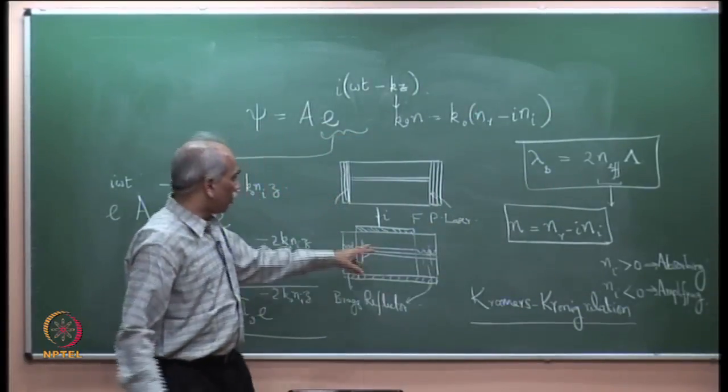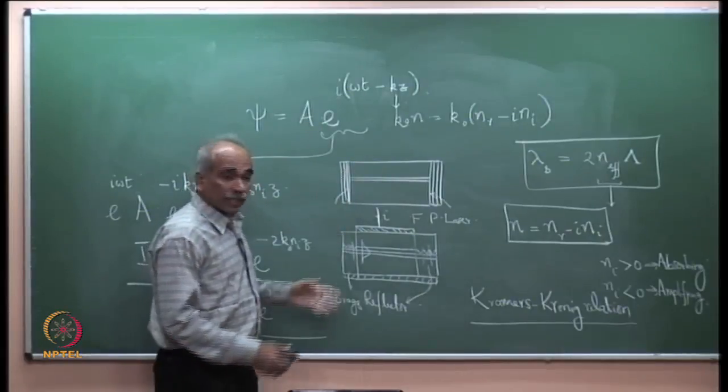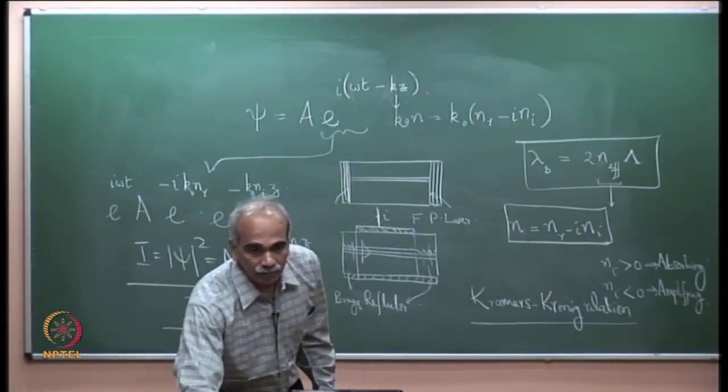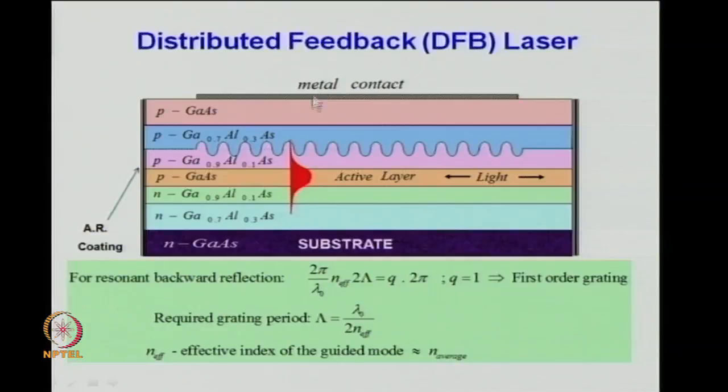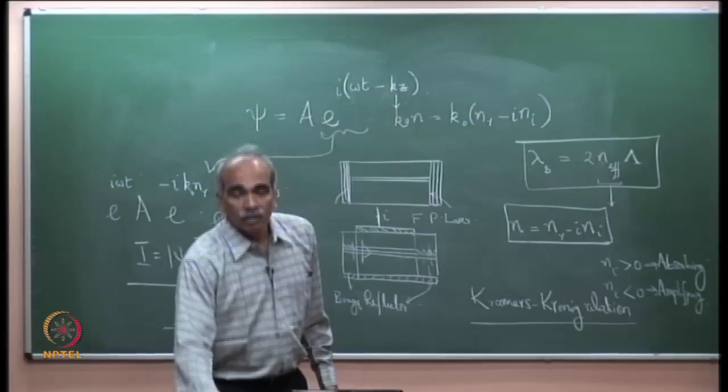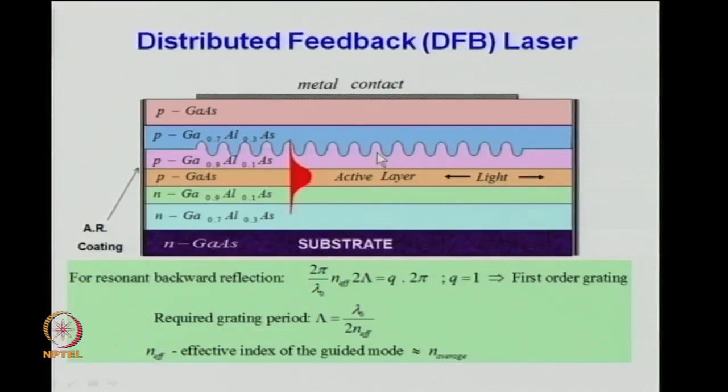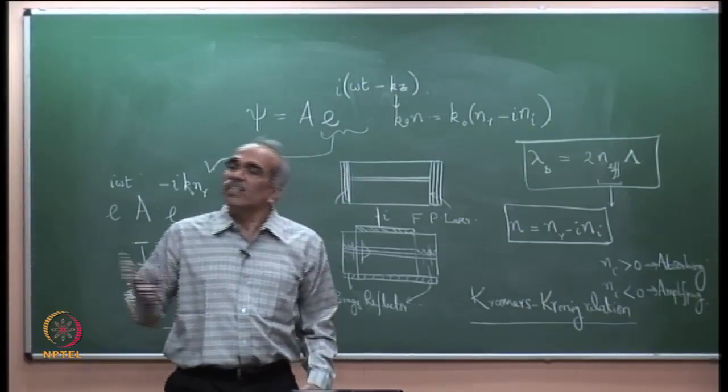In the case of a DFB laser, this is the DFB laser, the current is passing through the grating which is selecting the frequency. Because the refractive index of the medium here changes due to injection current, the frequency also changes with injection current